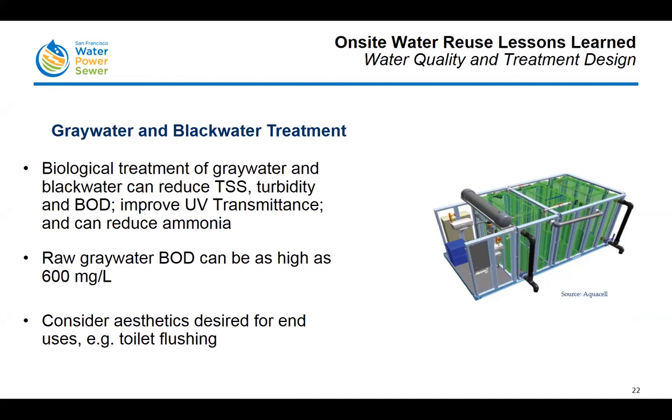One of the interesting facts that we've learned about graywater treatment is that the incoming biological oxygen demand, or BOD, in graywater can be quite high. That's not something we traditionally thought would be that high, because what typically causes high BOD is found in blackwater.